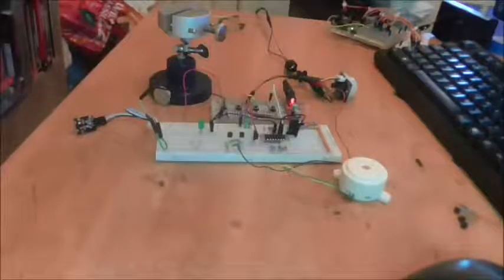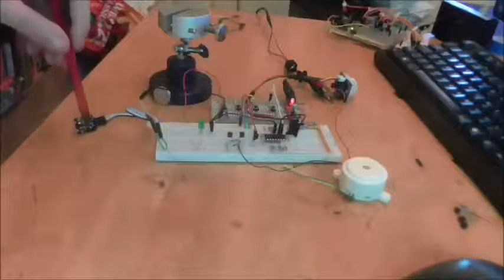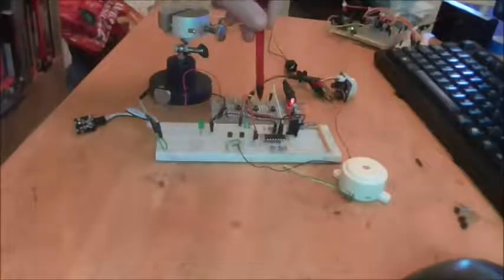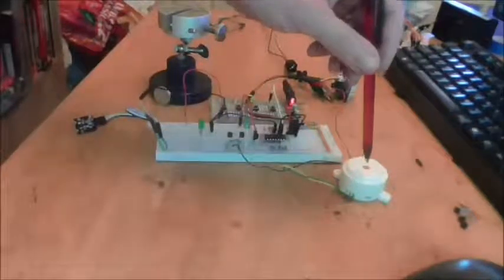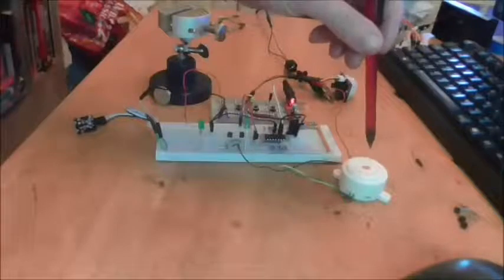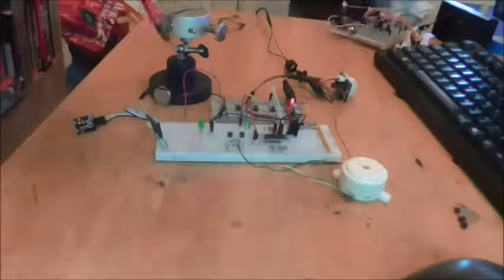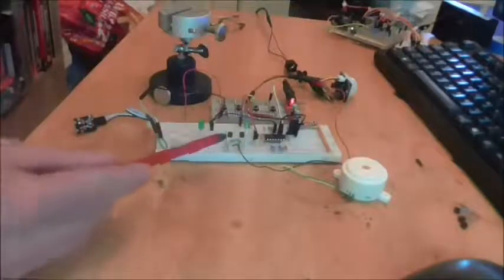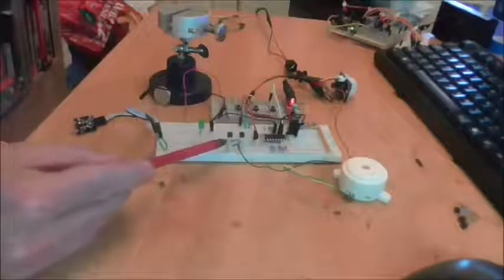So then, for our final breadboard proofing of the NAND system, we're putting our original components back in place. We have the PIR sensor here, the door window lock here, and the pressure mat, or the simulator thereof, here, and of course the large horrible siren is making a reappearance. The large horrible siren is working off a 9-volt supply. It's being driven by an extra transistor I put in because I wanted to keep that LED there so that we could have sound and light to drive the 9-volt system.